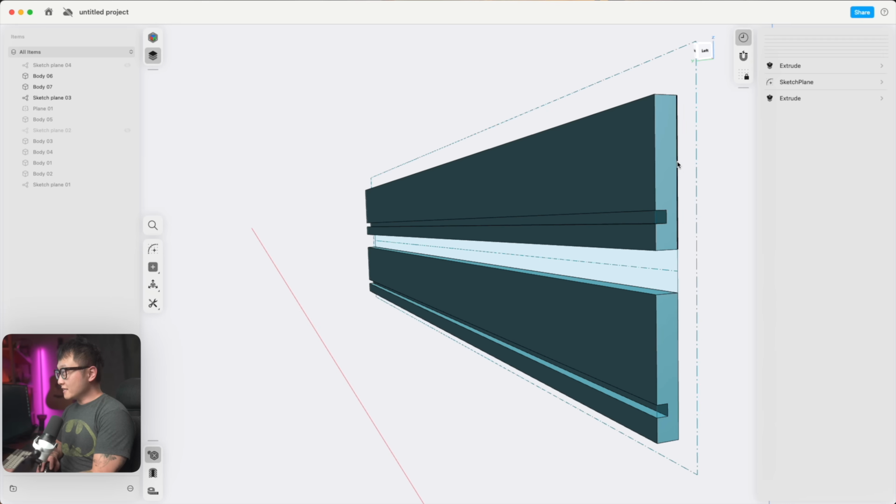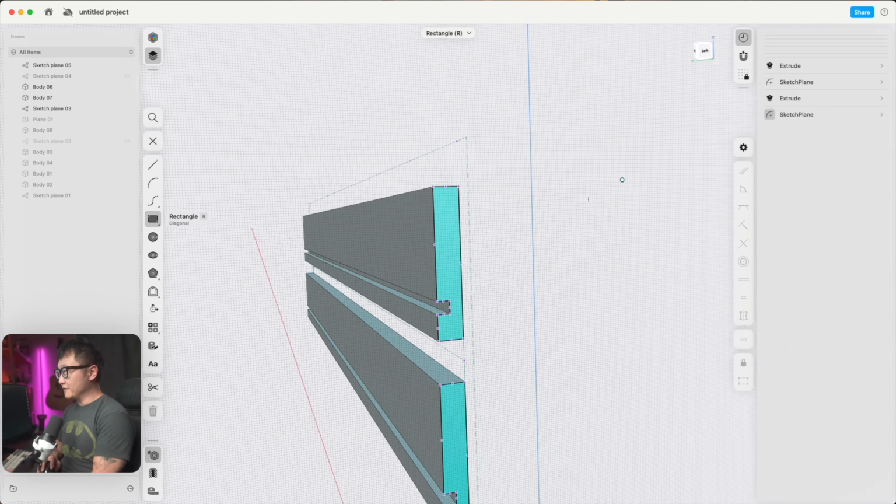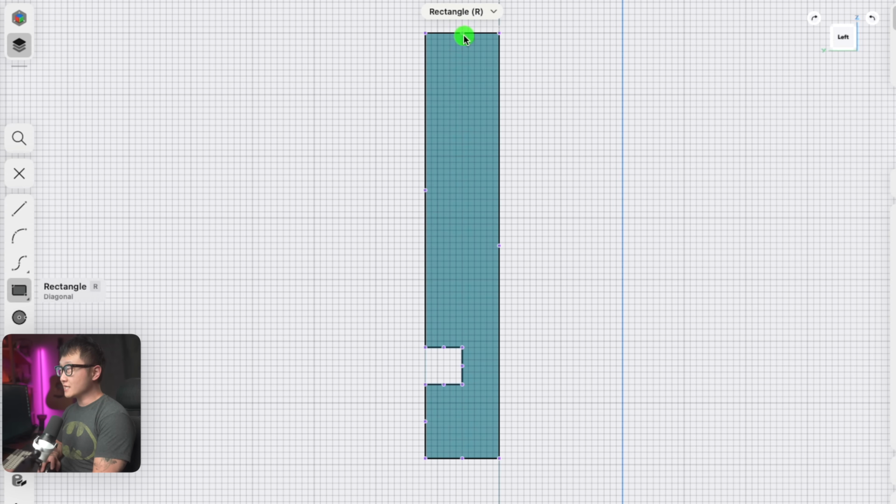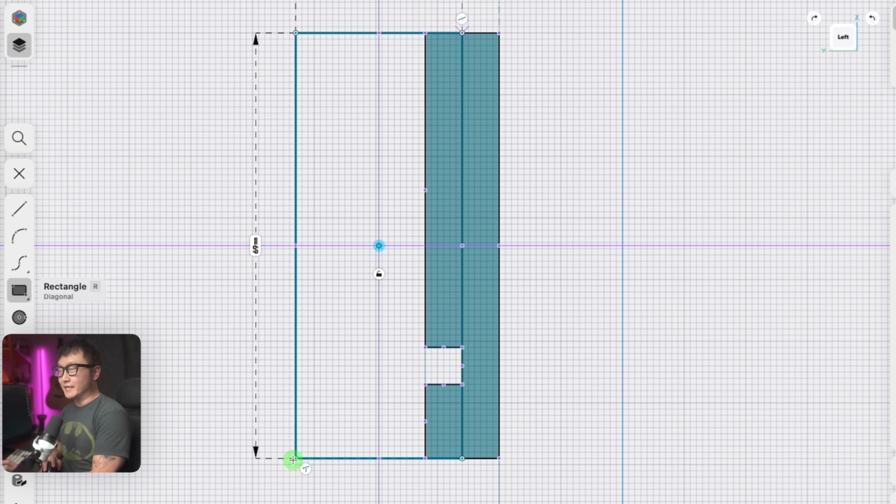All right, let's click on this left face, and we're gonna draw a rectangle, and this time we're gonna start from this top midpoint to this bottom midpoint. But before we click, we just wanna move our cursor toward the left so that it stays on this purple line. And this means that the height of this rectangle is now snapped to the height of this front panel. And once we've moved it outside the face of that front panel, then we can click to set it in place. And you know that you did it right when you see this little coincident constraint down here.